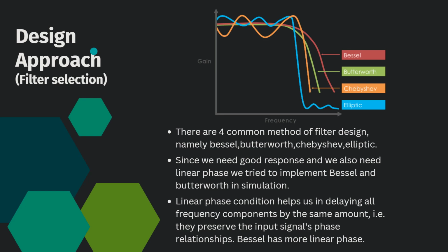As we move on to the next, in the DSO plots we have a constraint of the DSO here. The DSO was unable to show the frequency Bode plot at less than 10 hertz. So we could not get a complete Bode plot. To ensure that we show that the high pass is working, we attach the plots here.